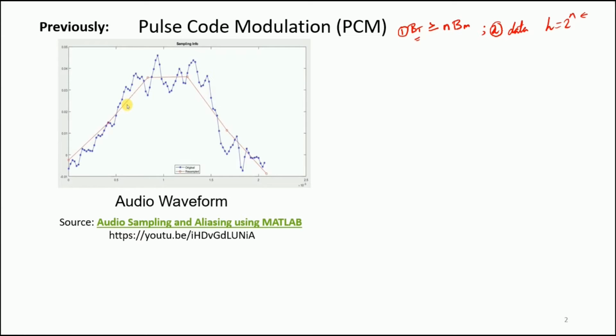But you can observe that the difference between the samples is very small. So we need to come up with a scheme in which, rather than sending the information for all time periods, we send another relative information, for example the difference between the symbols, right? So in short, PCM is not very effective, or rather not very bandwidth efficient, because of large n, due to which our transmission bandwidth increases. So in short, there is very small variation in between the symbols.